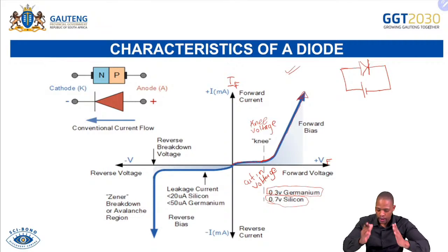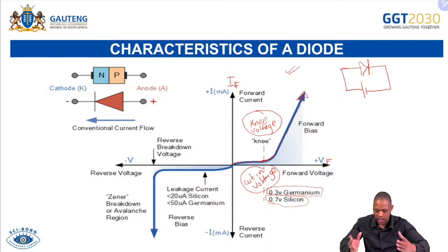What you need to know is that the minimum voltage that is needed is knee voltage. So you need to know its name. It's called knee voltage. You need to know that it's also called the cut-in voltage. At this point, the diode will start conducting electricity. Remember, it starts by not conducting, it reaches knee voltage, then starts conducting. That's why you see this graph just simply increasing linearly in this case. So that's what happens in a forward bias diode.